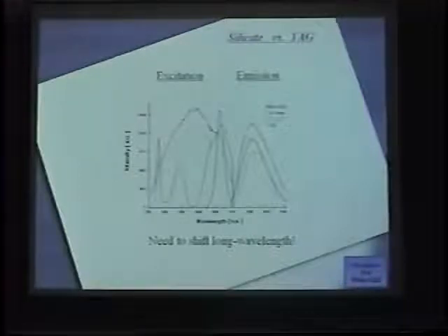See, this blue color is YAG phosphor. YAG is a very famous material. A long time ago they used that YAG material in CRTs. But very fortunately, near 465 nanometers, they can absorb a lot of photons in this energy band. Also, they emit the orange color here.